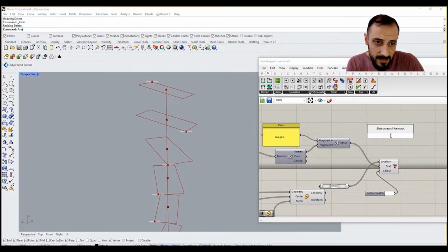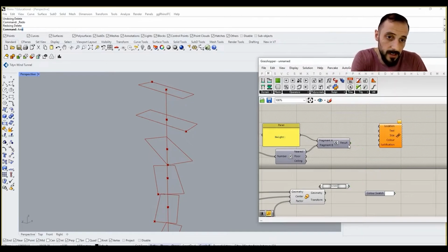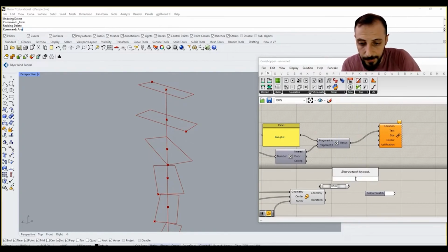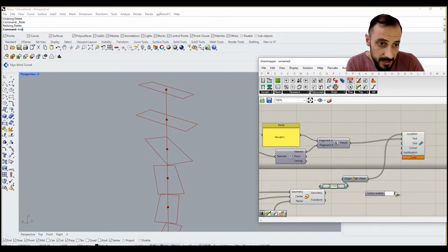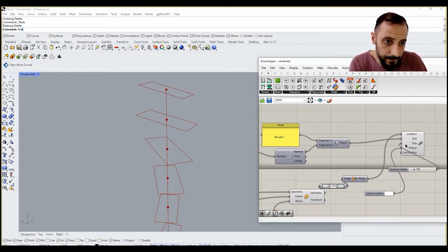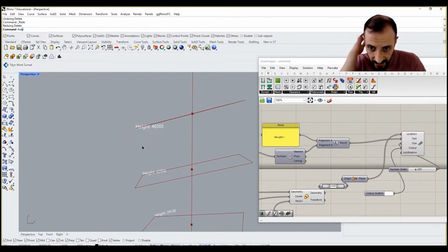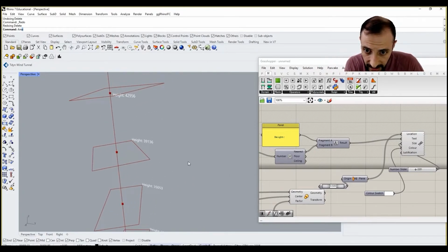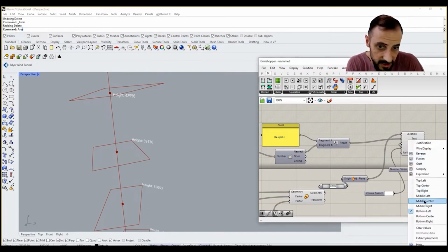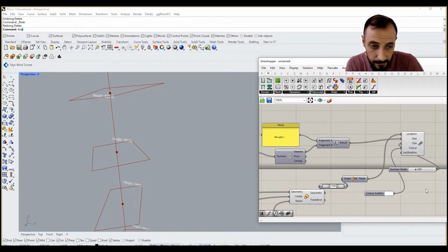Or what we can do is put a tag 3D, as you already know. So we can put this text, and we can put an XYZ plane on each point here. Preview all off. This is my location, this is my color, and the size, let's say 150. Is it too small? So we check each and every curve's height by looking at this. Of course, you can change the justification as it is, or you can say mid right, mid left. It's completely up to you.